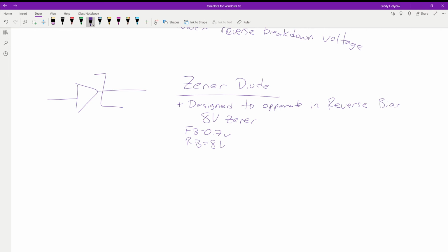So when you put them in power supplies, you could put in a 12-volt battery, run it through the system. You could put in an 8-volt Zener and a 4-volt Zener, and you could split that down. What I would do is I'd put the 8-volt Zener in, and then I'd put the 4-volt in parallel with that guy with a couple other resistors and kind of make a loaded voltage divider, which then can split my power out. And it'll keep it fairly constant.